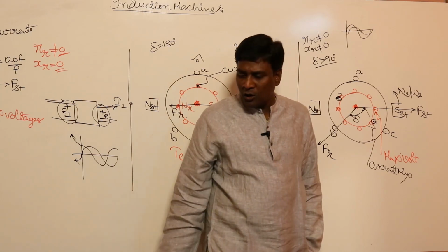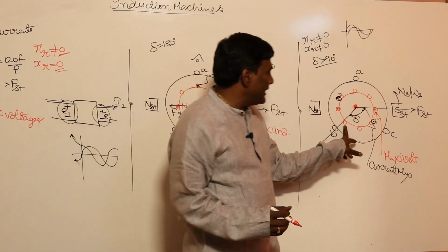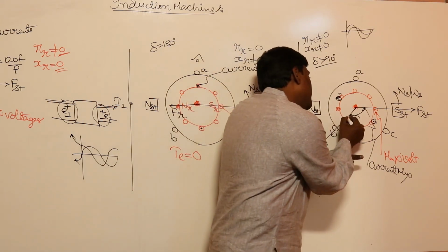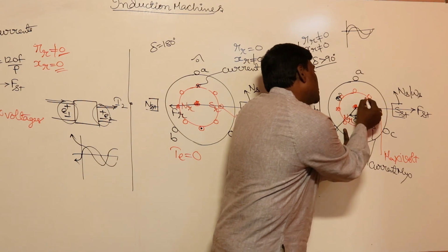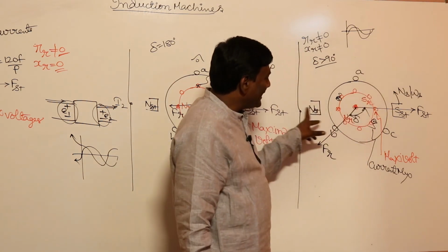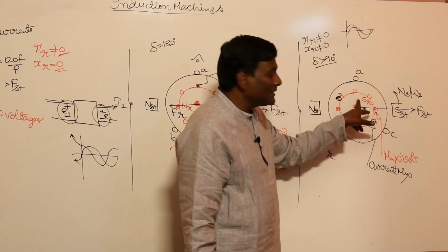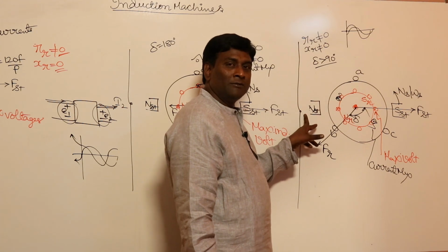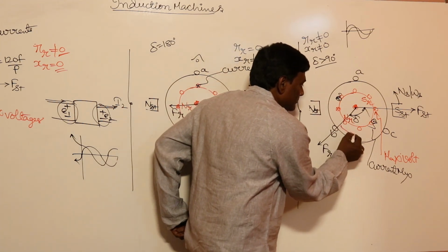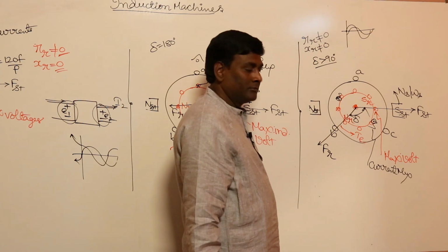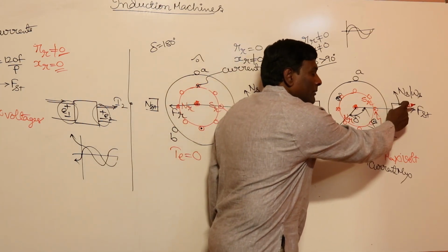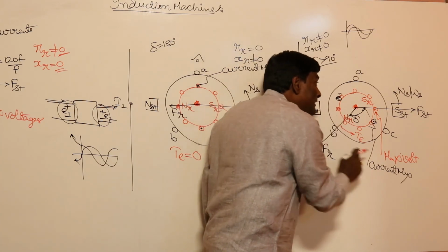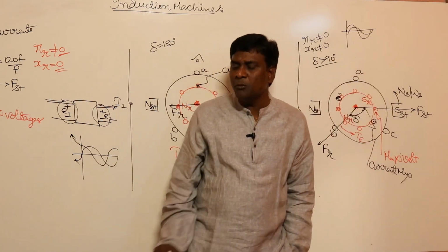Now let us think of how the pole formation is. If you sit in the air gap, MMF is coming out, flux should come out. So it should be north pole of the rotor, and south pole of the rotor. Now N repulsion will be there, S repulsion will be there, and S attraction and N attraction will be there. So torque will be developed in this direction. If my stator RMF is rotating anti-clockwise, my torque is also developed in the same direction. Means that it's a motor.